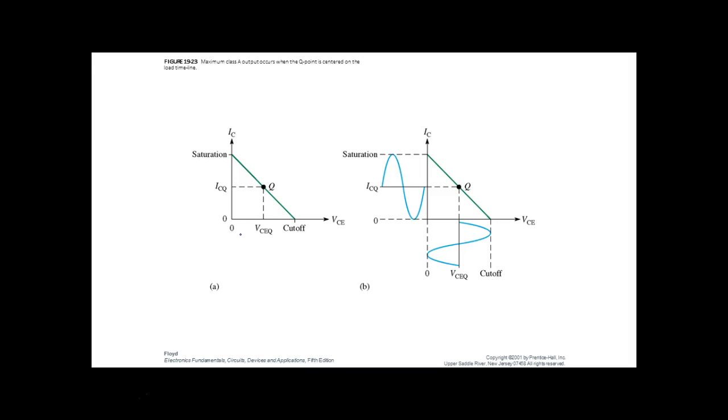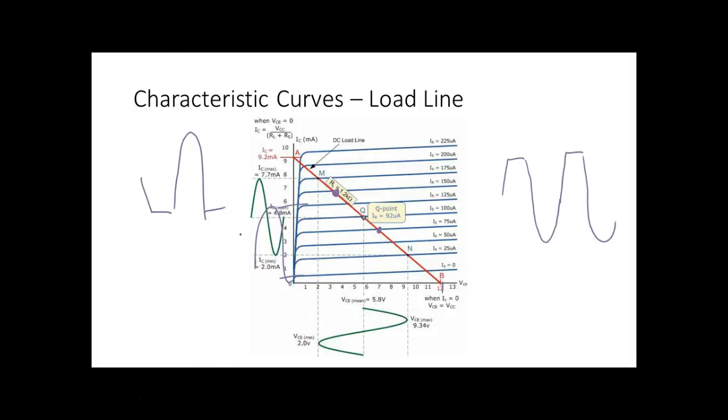They don't show the characteristic curves, which would specify the base current that you would put on. If you were an engineer designing this, this is what you would use right here. Well, the problem is that they don't give the collector characteristic curve so you could do the load line. So you have what they call curve tracers, which literally does exactly what we just did. It automatically comes up here and it'll draw it up on the oscilloscope for you. And so you can get those.